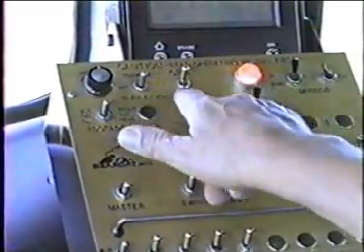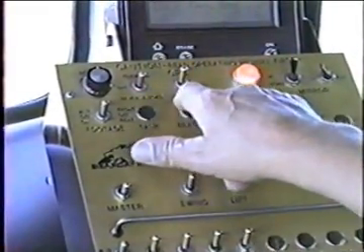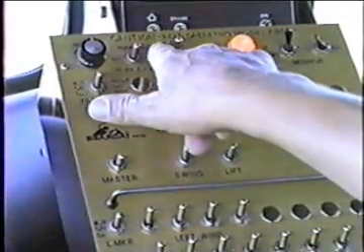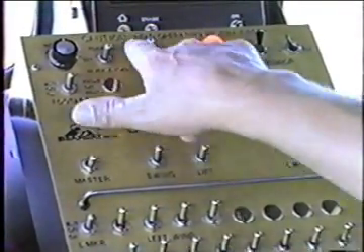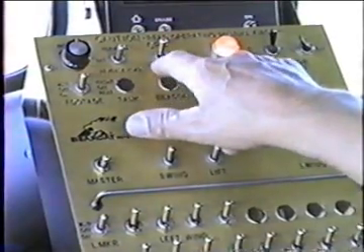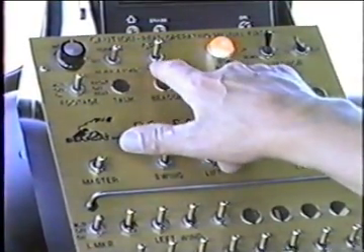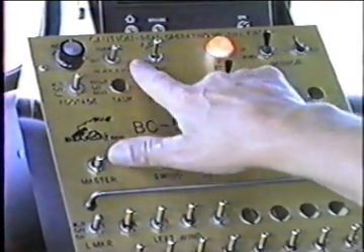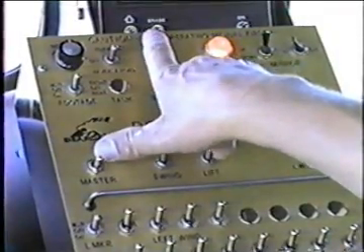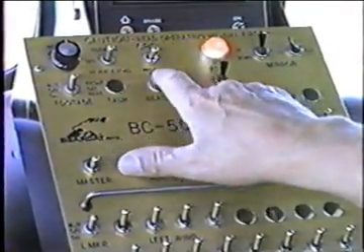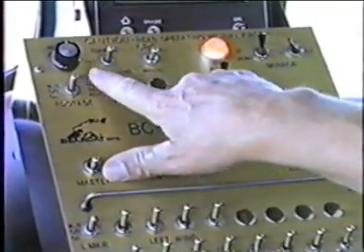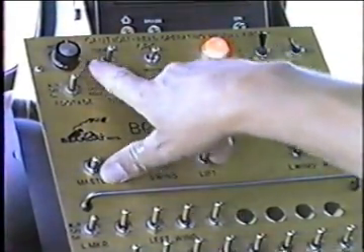Switch says CRC and manual. Any time that it is in the CRC position, that's for computerized rate control, the computer manages the speed and the direction of the pump. That particular switch has a second position, which is manual. In the manual position, then we can control the direction and the speed.